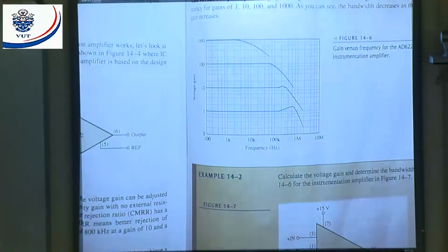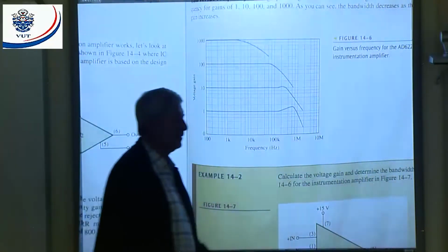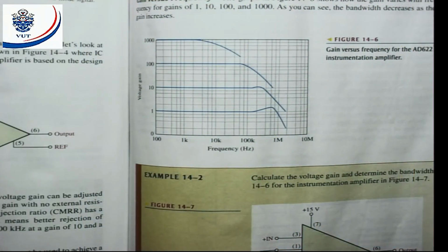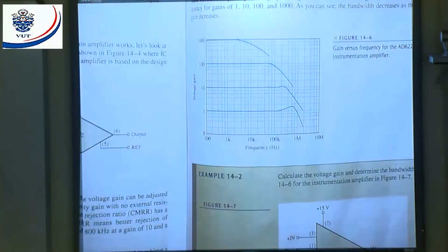But if I ask you a question like that, I will make sure you will give me the correct answer. All right. They say approximate. Now, if you look at the newer books, some books they talk about 60 kilohertz, and then they move it to 80 kilohertz. I don't agree completely. That means I will say it's closer to 100 kilohertz according to me. All right. But you must use the right graph. You must first go and calculate the voltage gain, and when you know the voltage gain, you can go and find your bandwidth. All right.